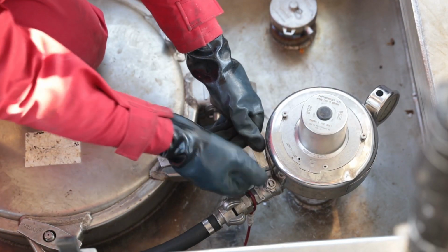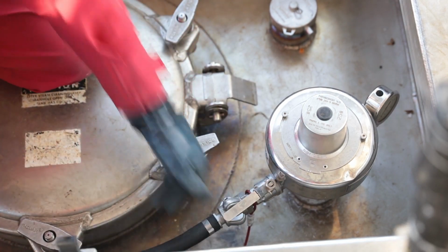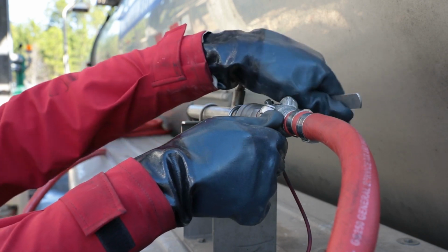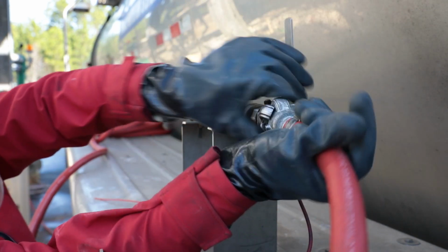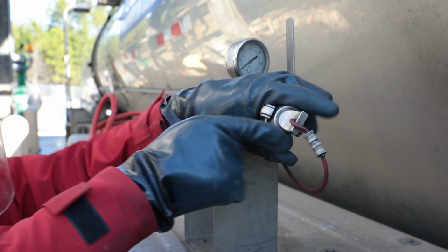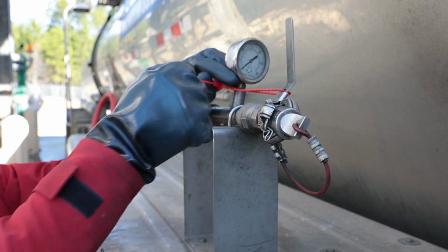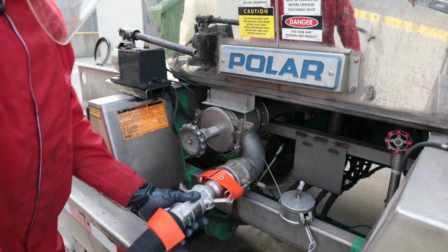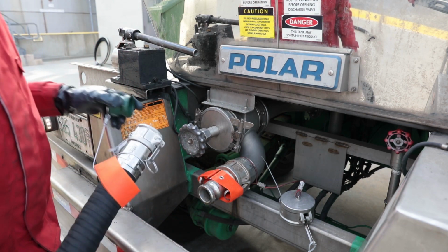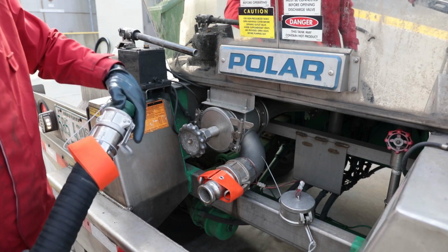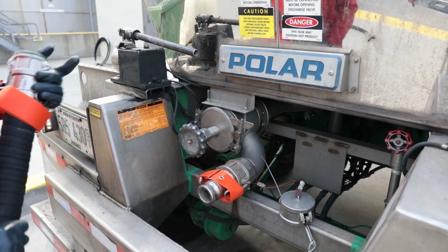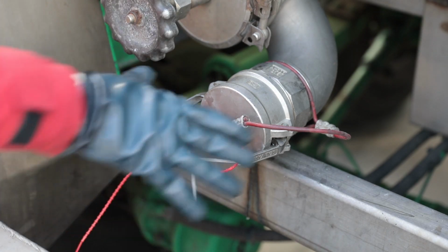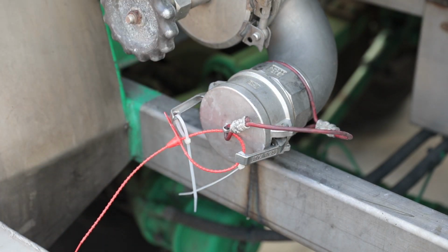Bleed off the air pressure in the truck using a top opening before leaving the unloading area. Relieve the pressure from the transfer line and then carefully remove the loading hose away from your person. Replace the outlet caps, secure the dome lid, and close all valves.